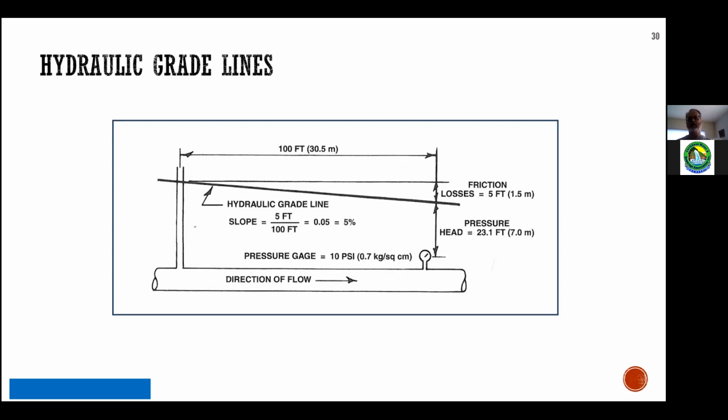But the head loss, which is that line, the gap there, was so great that the grade line actually dropped and stranded the 2 top floors. It was a 3-story house. The 2 top floors of the house had no water, simply because of the grade line collapsing so far. So as operators, we got to think about all of the things that we do, or the conditions that our system has built in that can, how should we say, sacrifice energy. And it's all about preserving as much energy as possible.